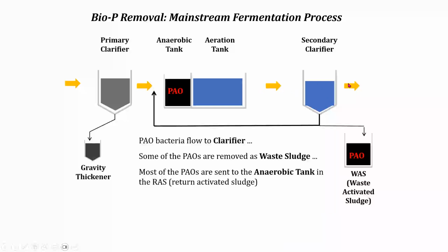Re-release happens more in the summer, in warm water. So we're going to want a lower sludge blanket in the summer weather. We're going to want to make sure there's no settling in the channels, our UV, our disinfection channel. We don't want any phosphorus to get re-released after we've worked hard to remove it in these two zones.